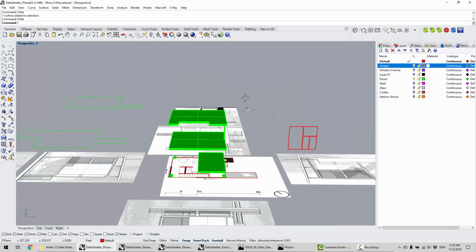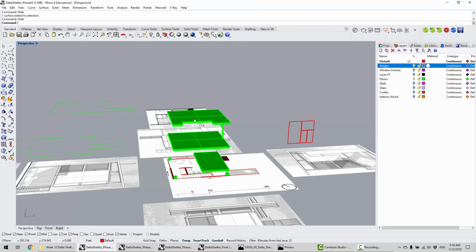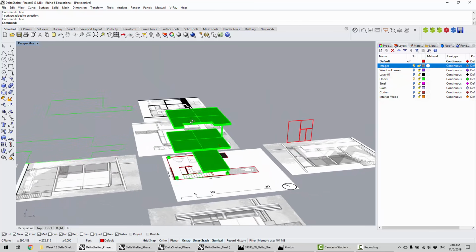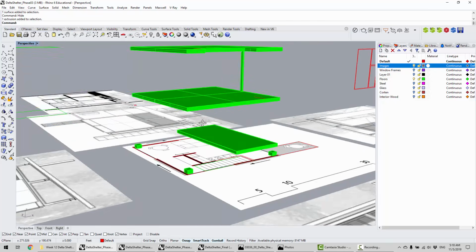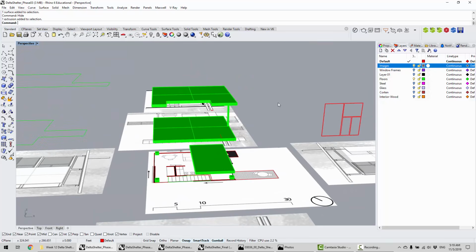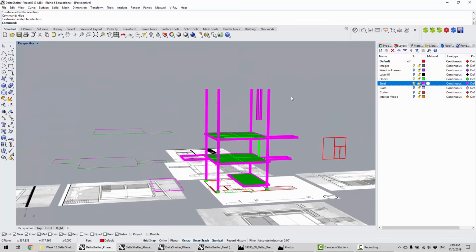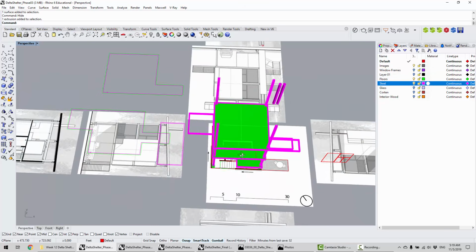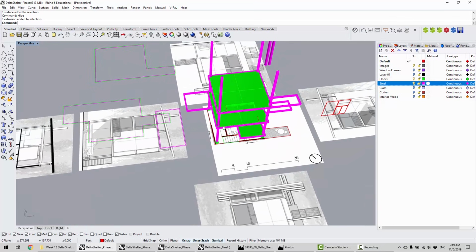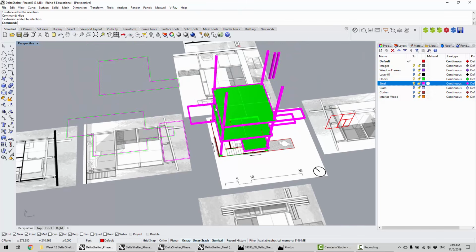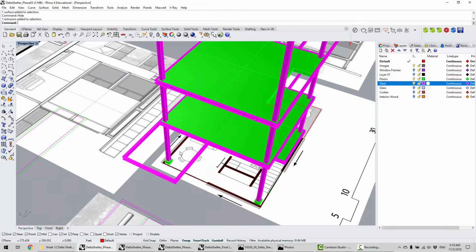Okay, so the first order of business is to get the outline of the floor slab in place, and get these footings in there, right? You'll see the 4 steel columns are embedded in there. So essentially you just zoom in and trace one of the outlines. I think it's maybe in here somewhere.